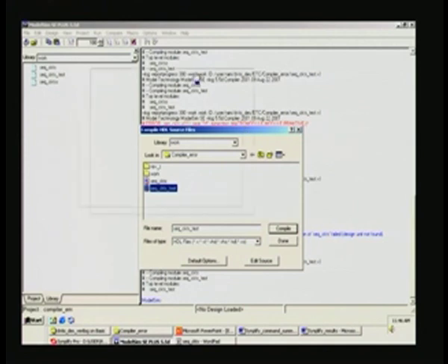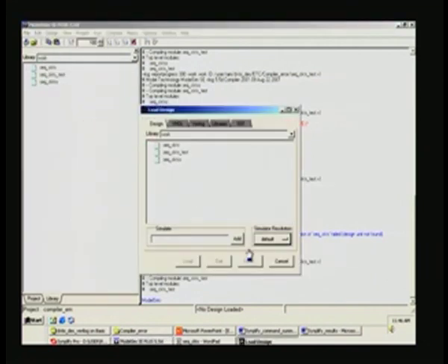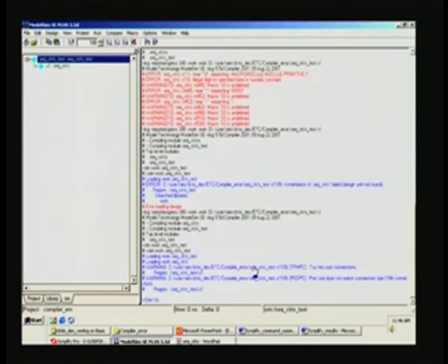In fact, there are no errors here, right. So, let us see whether an error is reported during load. Yeah. So, too few port connections it says, right.